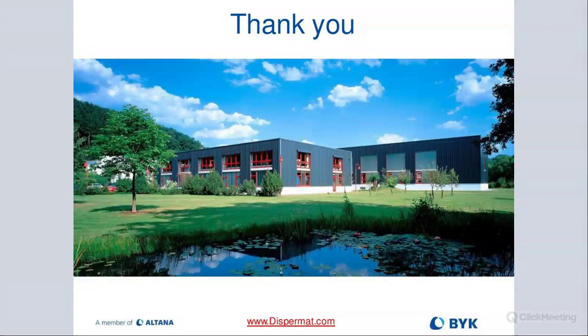Are there different types of blades for varying viscosities, or does one blade work for everything? So the blade, yes, there are different blade types, but different blade manufacturers swear by their own proprietary design. We have one standard design that we use for almost all viscosities. What we are looking for is, if the viscosities increase, then we just proportionally increase the diameter of our blade, because we want to ensure that we get proper movement of the material inside the container.